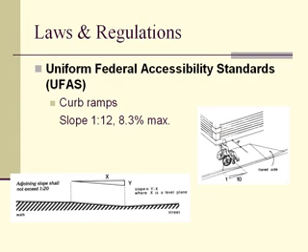Another requirement, following the line of the accessible routes, is the curb ramps. And these we'll see often, basically provided when people have to navigate through curbs and when people need access from parking spaces onto sidewalks and then to the facilities. So the main premise here is to provide a slope that is no more than 1 in 12.